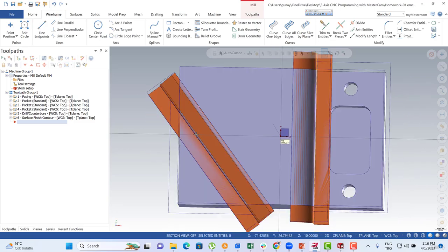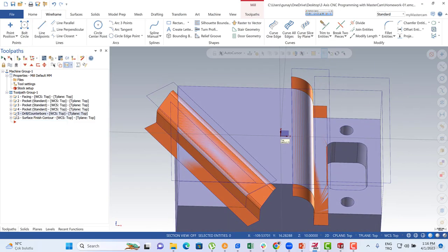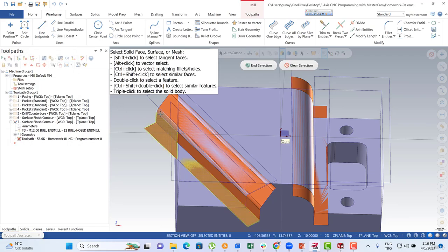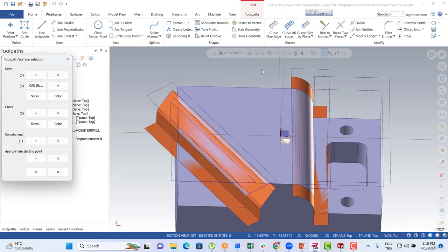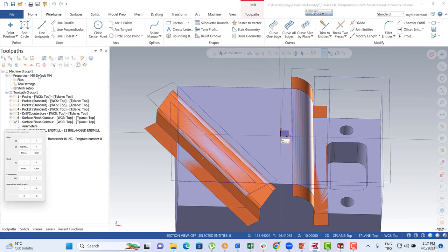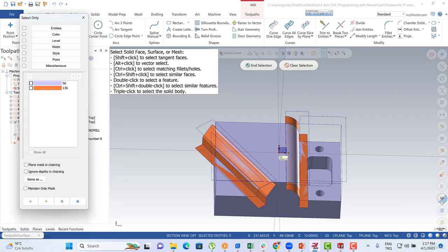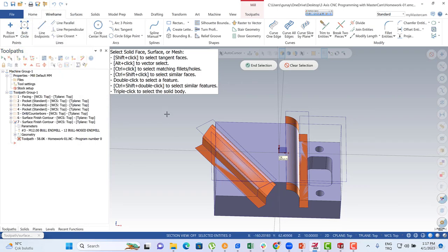We have the boundary and face, and then let's create our toolpath. So I can copy that toolpath and paste it here. We can turn to the geometry. I can delete this one and add a new one. Oops, sorry. And actually, let me turn to here. This is the all entities or only entities. I prefer to use the only and this one. And then we can get the rectangles and hit the OK button.